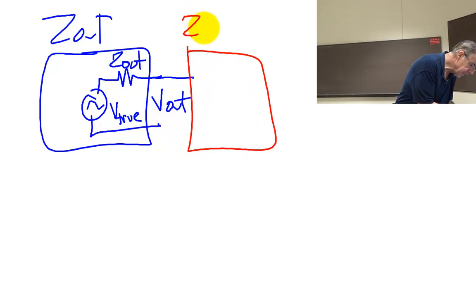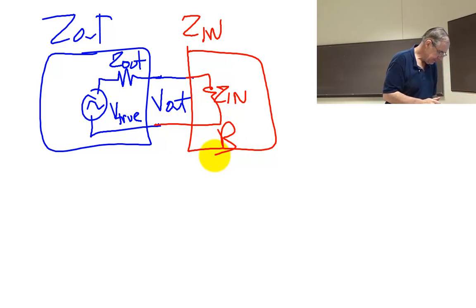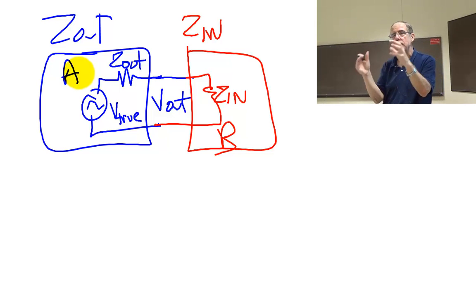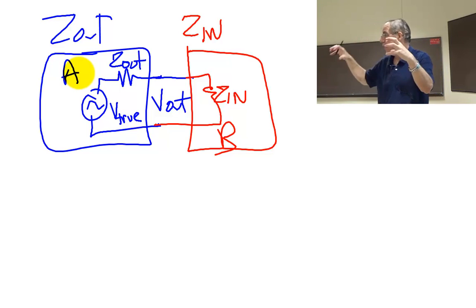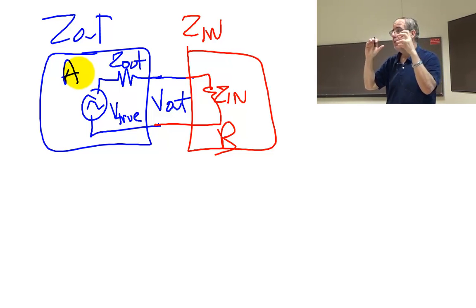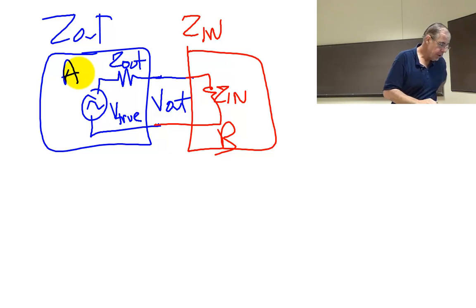And how this is important is typically we'll connect the module B input to the output of module A. And so what was the guiding force to input and output impedances that we saw last time? There was a guiding equation. It's going to show up on the test. It'll show up in life. When I connect an analog module to another analog module, I have to think about impedance. Because where's the error in this system? Where's the error? Across Z out. So this represents an error.